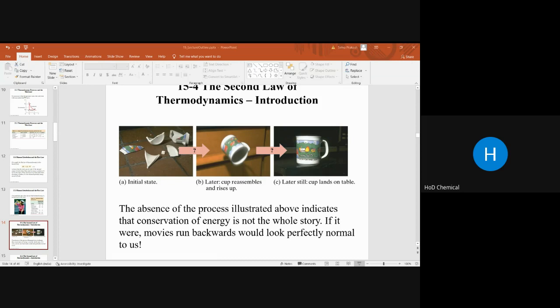And the next one is be careful about the units. Be sure that you are using the same units throughout the problems. Express the temperature in Kelvin. The next one is efficiency is always less than one. Entropy increases when heat is added and decreases when heat is removed.